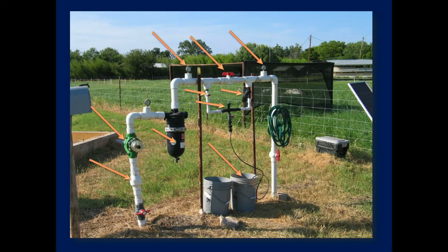Now, obviously, if the well is just turning on and you're filling up your lines, this won't work well. So it's got to have a nice constant pressure. These Mozzies are designed to work at certain pressure levels, so you can get them all over the board in terms of whatever the particular situation is you're dealing with. You want to make sure you get the correct injector for the flow rate, so the number of gallons a minute going out through the system, and the pressure and things like that.